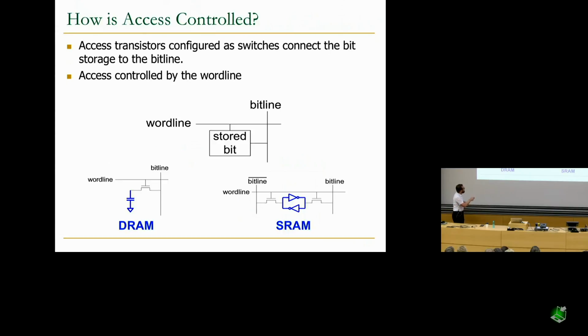And this capacitor is really, really small. The charge on it is extremely small. That's why you design it very carefully, and you have very little perturbation on the bit line. So you need to have a very strong sense amplifying circuitry to amplify that little charge perturbation. As a result, this is a really small circuit. The sense amplification circuitry, which happens to look kind of like that actually, is 100 times larger than this. So you can pack many, many DRAM cells in a single row and in a single array.